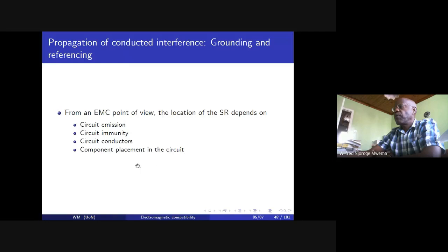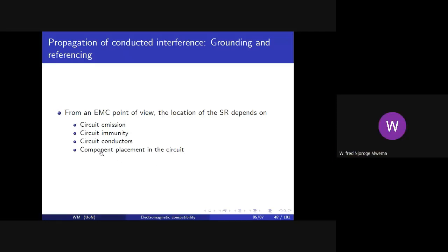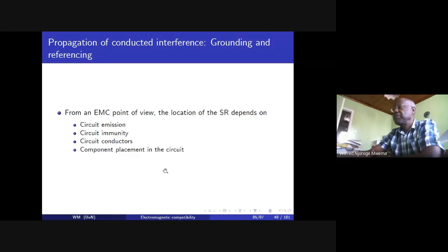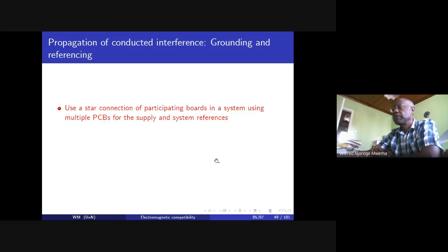Say, for example, you have your analog or low frequency circuit, then you have a high frequency circuit directly in the path of the others, and then you have the low frequency circuit at the output. What would happen is that these are going to cause a lot of interference. Therefore, you want to make sure that you never put the high frequency circuit in between two low frequency circuit portions of your system.